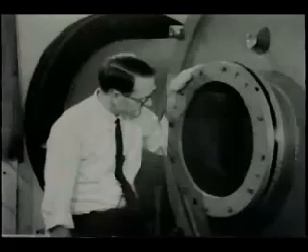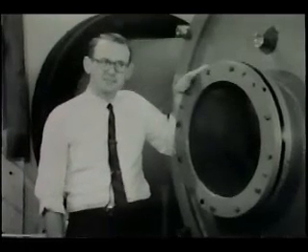We shall probe the inside of the shock wave with this tiny wire here. This half of the wire is iron, and this is constantan. So we have a thermocouple junction in the middle. The wire is small enough to be in free molecule flow whenever we place it in one of the shock waves we've just seen. It's also small enough so that it doesn't disturb the shock wave by its presence.